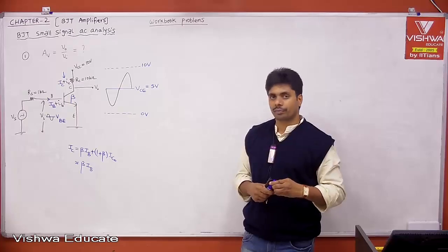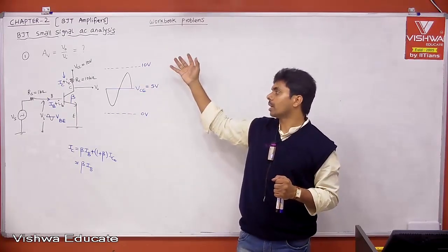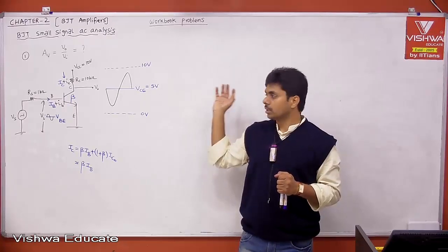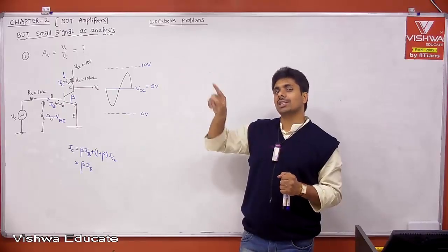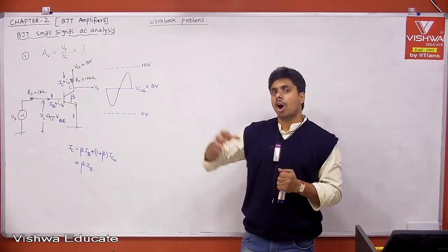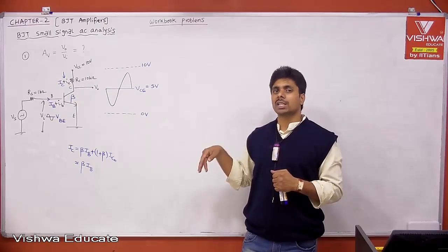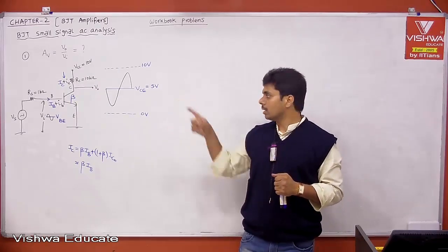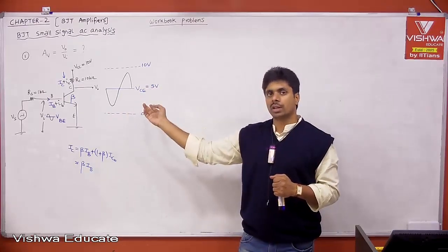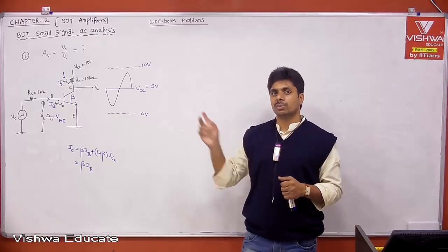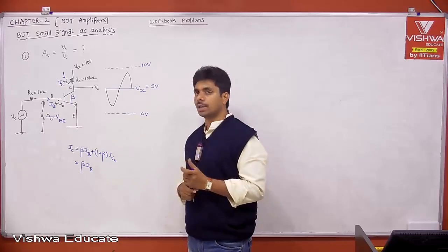Write down. I think I explained what current gain is. 40 times your input current is your output current entering into your load, and 400 times your input voltage is applied to your load, but the minus is indicating the direction. In the case of current gain, the actual current is opposite to the expected load current entering the load, that's the minus. Your output is decreasing when input is increasing, which is the inversion. That's why the minus indicates inversion between output and input. But magnitude wise, output peak to peak divided by input peak to peak is your voltage gain.